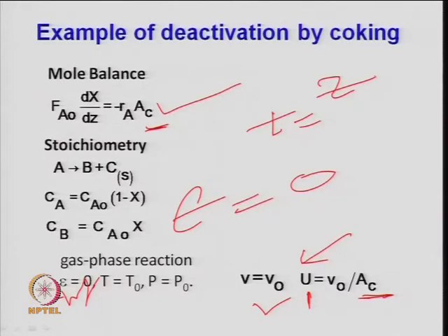superficial gas velocity, right. So, the time required in a reactor will depend on the length of the reactor divided by the velocity of the gas, right. So, that is the height of the reactor basically, or one can design the height of the reactor or size a reactor if these two things are fixed and the conversion is fixed, right. So, we will talk on that. So, I stop here and I will continue next time.